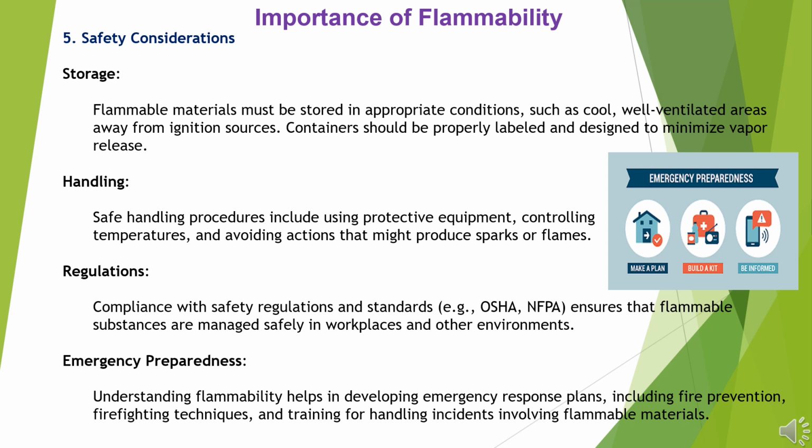5. Safety considerations. Storage. Flammable materials must be stored in appropriate conditions, such as cool, well-ventilated areas away from ignition sources. Containers should be properly labeled and designed to minimize vapor release. Handling. Safe handling procedures include using protective equipment, controlling temperatures, and avoiding actions that might produce sparks or flames.